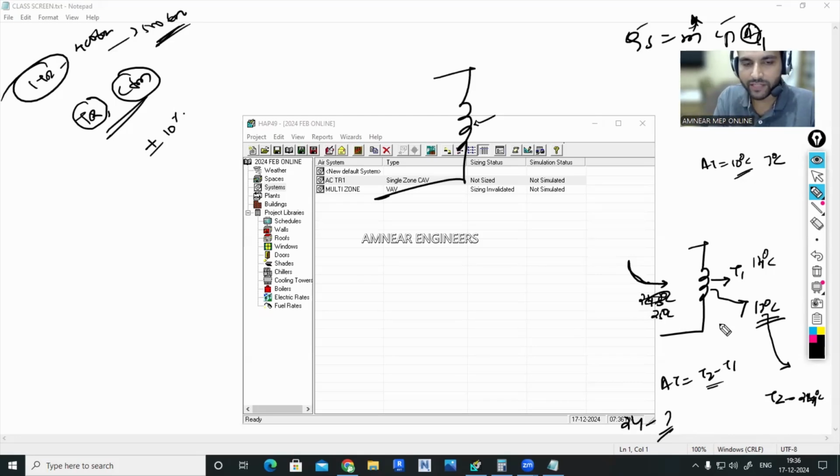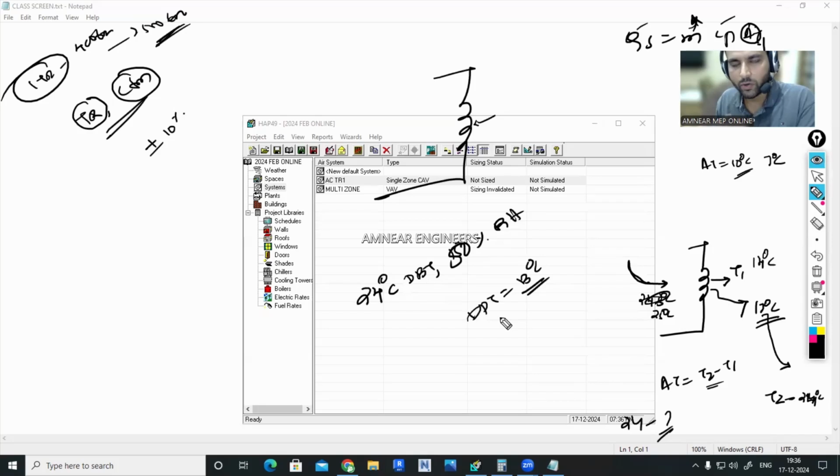For example, we have studied in the psychrometry classes for comfort air conditioning systems, let's say 24 degrees Celsius dry bulb temperature at 50% relative humidity, the dew point temperature is somewhat near to 13 degrees Celsius only. In reality, when we are considering the room sensible heat ratio, bypass factor and all, this value will be slightly decreasing, or sometimes it can increase as well. Correct. Means you have to cool the air until this point, then only the effective condensation can come. But when the supply temperature is much higher than 13 degrees Celsius, latent heat removal will not come properly.